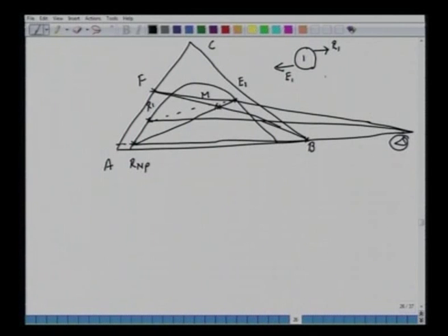So when you're connecting it, mathematically you are saying that again, this R1 and E2, difference between the two is a constant. Same as what we had for the feed and E1. So the difference in kg flow rate is the same. So we have R1, this intersects at E2, connect, find the tie line. This tie line need not be parallel. You have to read the equilibrium curve for y versus x. So we have R2 here. Mark this point. R1, R2, E1, E2.